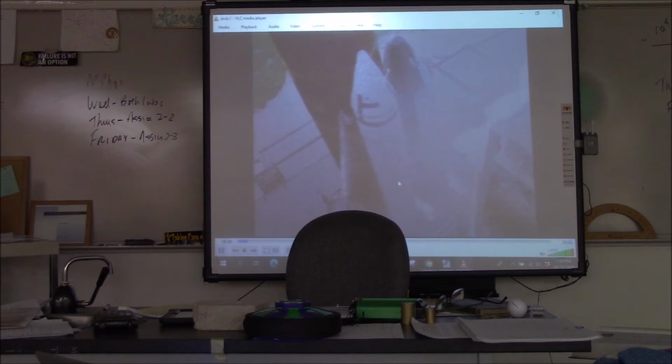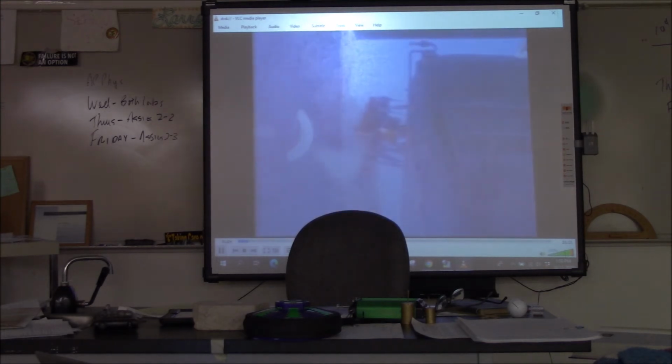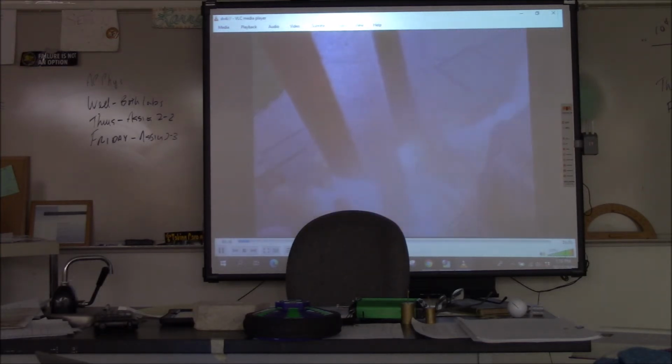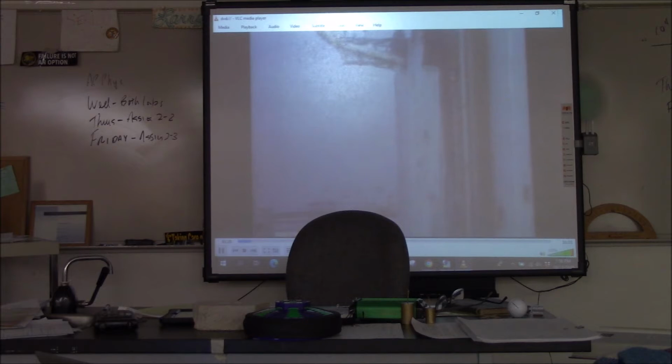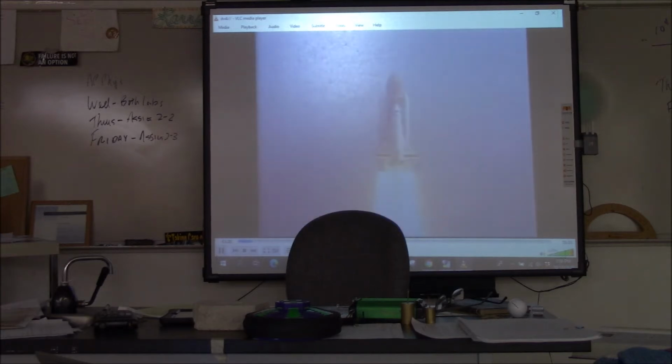And energy. From a physics viewpoint, a rocket launch vehicle can be thought of as a large force machine. Its sole purpose is to apply a continual thrusting force in order to produce an acceleration. If the rocket is to achieve a low Earth orbit, the magnitude of the acceleration which is required tends to be quite large. The rocket must go from a state of being at rest on the Earth's surface to that of traveling 8,000 meters per second at some given distance above the Earth. This tremendous velocity change takes place over a relatively short period of time and necessitates the large amount of energy and acceleration provided by a rocket launch vehicle.